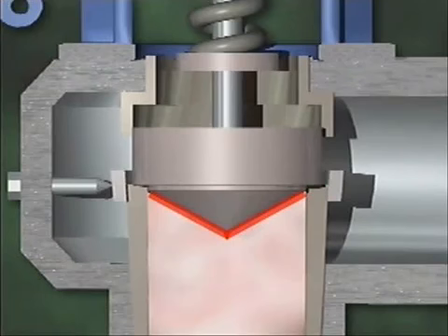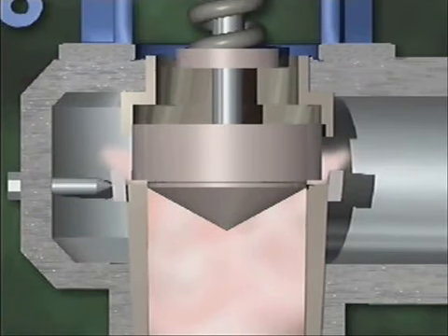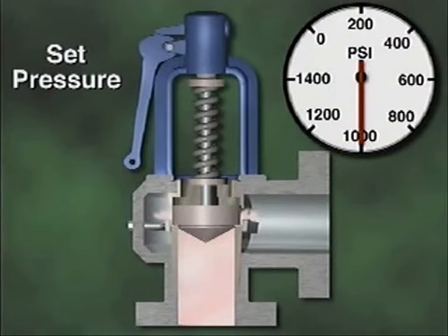The disc has a lip or shoulder that isn't exposed to system pressure when the valve is closed. The lip of the disc sits above the huddling chamber. The center portion of the disc, which is located over the valve's inlet, is always exposed to system pressure. The purpose of the huddling chamber is to help expose a greater area of the disc to escaping fluid when the valve opens slightly. The fluid pressure acting on the increased area gives a greater total lifting pressure against the spring.